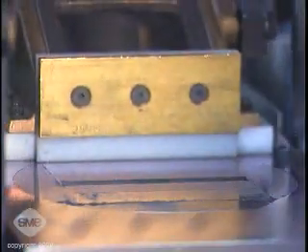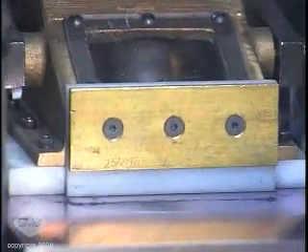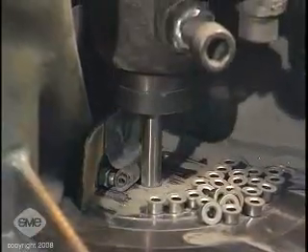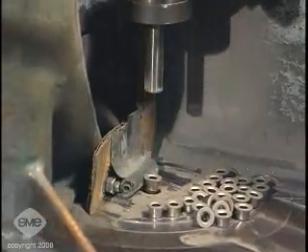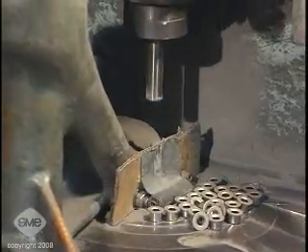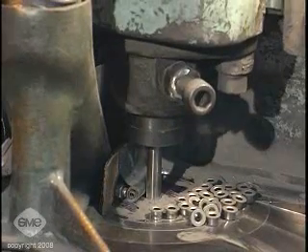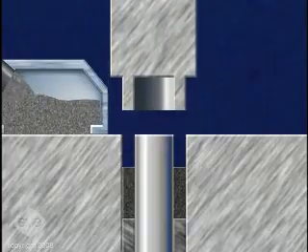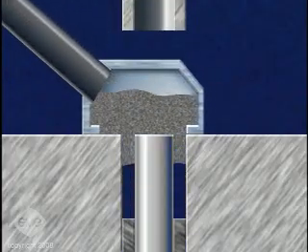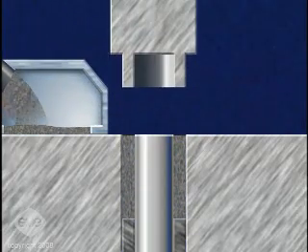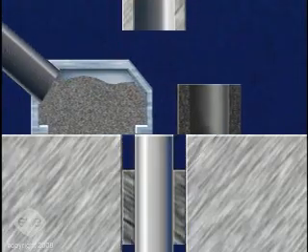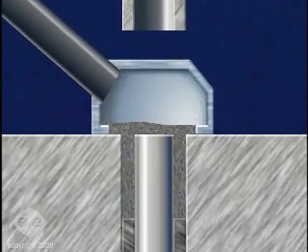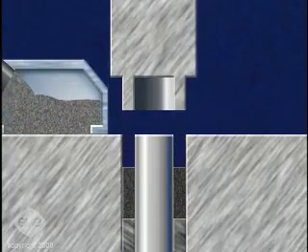Pressing is typically at room temperature, although elevated temperatures can also be used. Core rods are used inside the die to control formation of holes parallel to the direction of pressing. If the part being made is thin and uniform in height, the powder can be pressed from one side by the upper punch. When that punch withdraws, a lower punch raises the part out of the die.